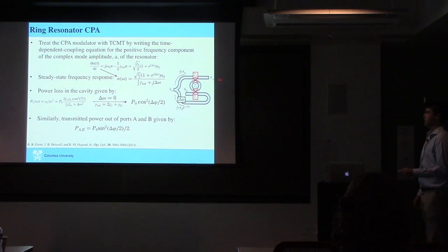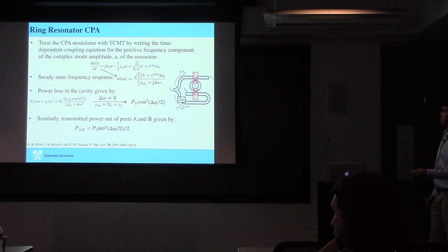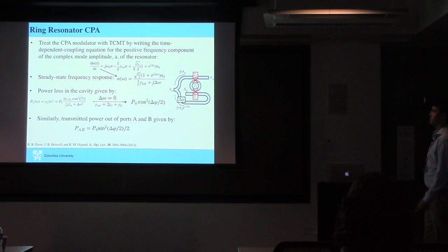If you have a silicon waveguide that you put near the ring, the evanescent wave will couple into the ring based on the resonance of the silicon ring resonator. So if you have a wavelength division multiplexed signal with a lot of different wavelengths, you can build the ring such that only one wavelength will couple out, and that's how they do a lot of routing and optical switching, and a lot of modulators are built this way now. So you turn it on and off based on voltage, and it has very low power consumption, and it's relatively fast and compact.